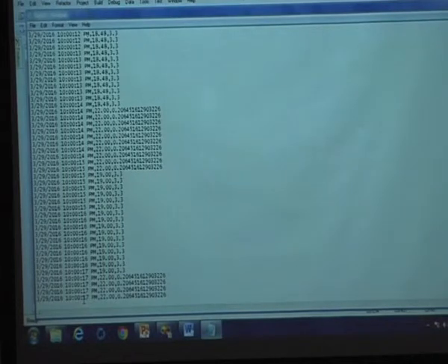But how many samples have we received? You can count, it will be less than 50 only. Then why are you unable to receive that many samples? That is the question here. It is not a research question, rather this is only a programmatic question. Can anybody try to highlight on this one? We configured for 50 Hz, 50 samples in 1 second, but in 1 second we are able to receive only around 20 or 30, on an average 25 or 26 samples only.